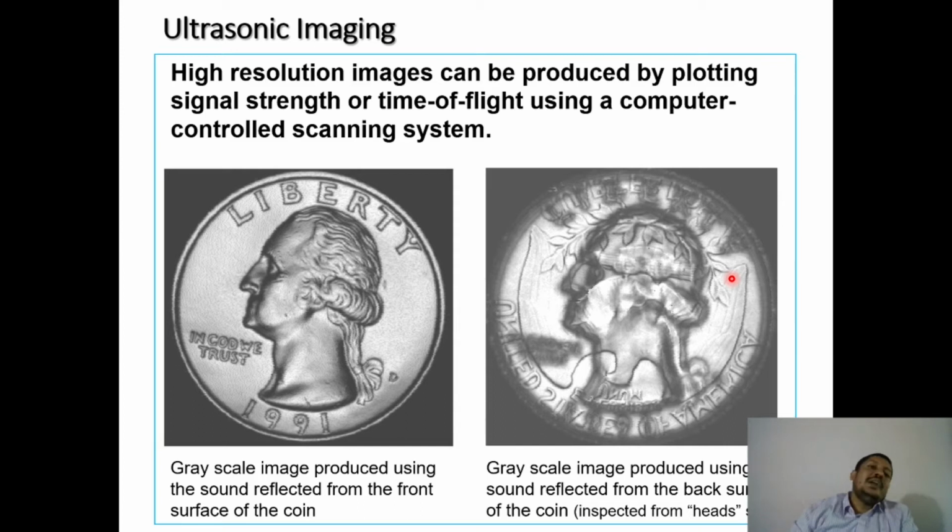So I have just given you an overview about weld defects and the reasons. Weld defects come from improper weld settings, improper material handling, improper environmental conditions, and sometimes the flaws inside your material may also end up as a welding defect.